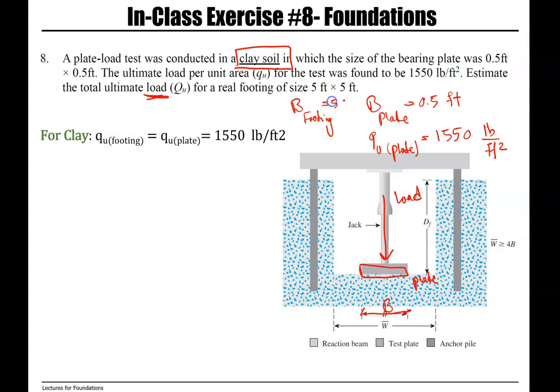If you go back to the beginning of this video, we went over the formulas which you can use to calculate bearing capacity of footing when we have the plate load test. So for clay soil, the ultimate bearing capacity of footing is actually equal to the ultimate bearing capacity of plate. That's only for clay.